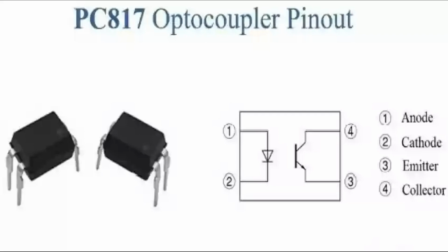Grounding and shielding. Proper grounding techniques and shielding can reduce the entry of external electromagnetic interference, EMI, and radio frequency interference, RFI, into sensitive circuits or cables. Differential signaling. In communication systems, using differential signaling, such as twisted pair cables, can help reduce the impact of common mode noise, where both signal and noise have similar voltage levels.